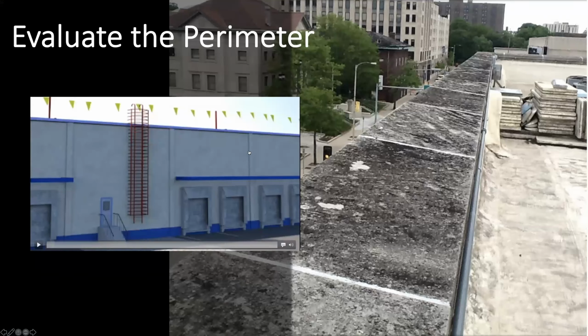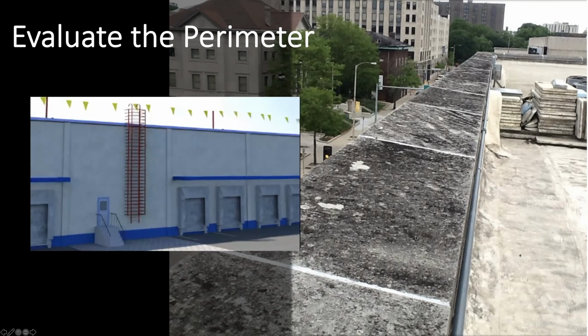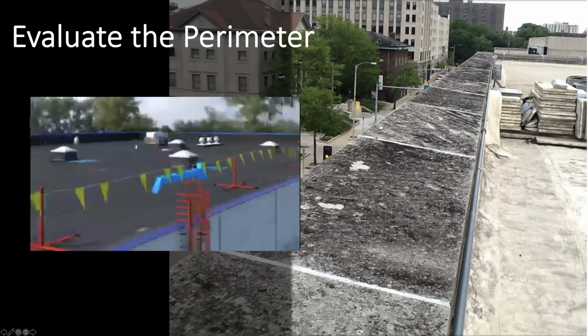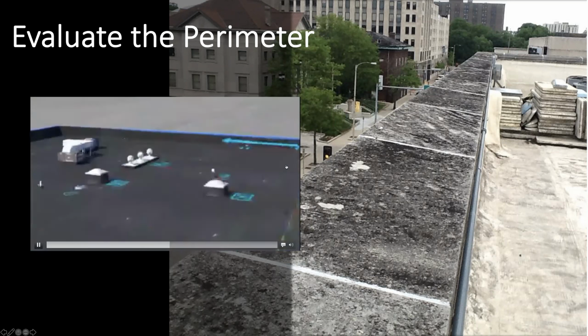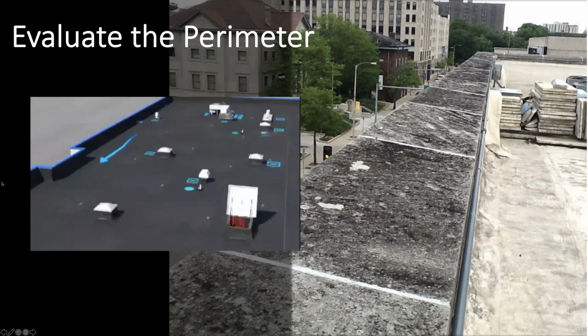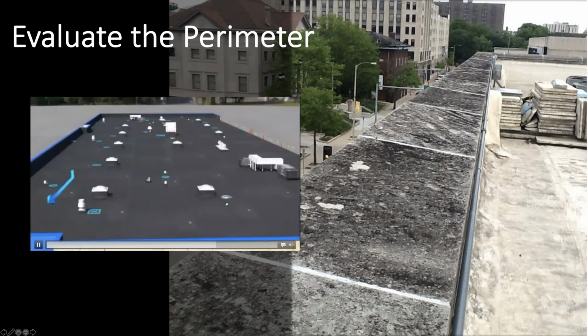Once done, take to the roof, either internal access or up a ladder, and with a systematic approach, cover the entire perimeter before you start getting distracted with other things on a roof, so you make sure you don't miss anything. And that includes either a drip edge, gutters, these types of coping systems, things like this, and make note.